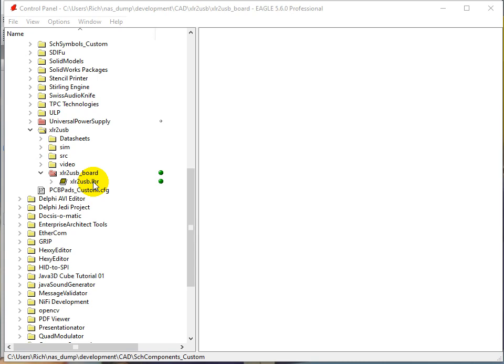which is we'll create a footprint, then we'll create a schematic symbol, and then we'll create a device or a component, or what I call a part, which is the connection between a schematic symbol and a footprint. As we build each one of these, we're going to rely on the data sheets quite a bit, as well as our own intuition on how it should work. So let's get started. We'll begin by opening up our library that we created last time.